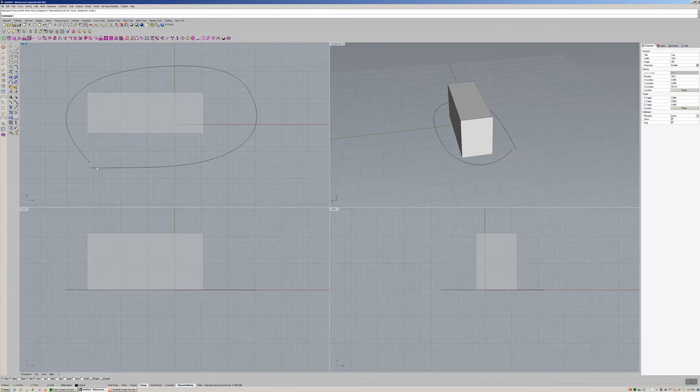Now, there's several ways of connecting it. So I'm going to start over again. And my favorite is interpolate points curve. It's the second one over here. Interpolate points. So if you go on the line, click it on, there's a second one over. That's the one that's like Illustrator. So when you start to use it, you'll see that the curve works like Illustrator almost, and you're able to shape around.